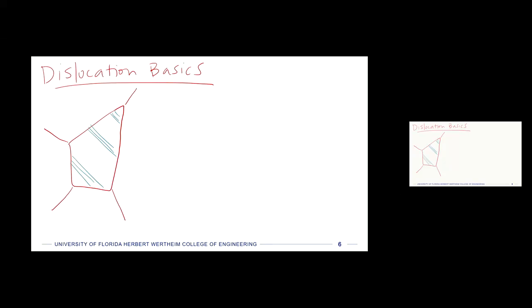And you'll see the bands that tend to go all the way through one grain, but they usually don't go over onto the next grain at the same angle. And that's for two reasons. The first reason is the next grain might have a different angle of its crystalline structure. So it's hard to change direction with dislocations, right? We'll talk a little bit more about that in the next class. But they like to go in one direction, okay?